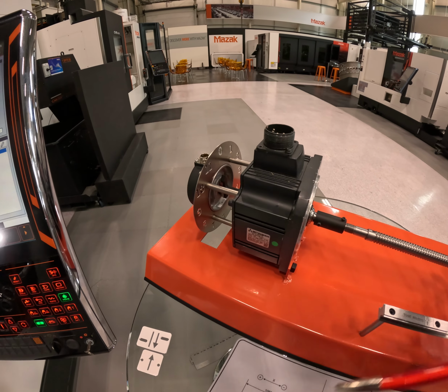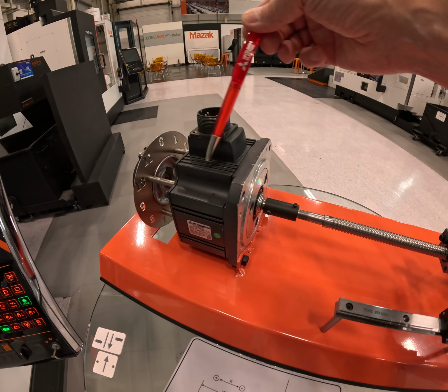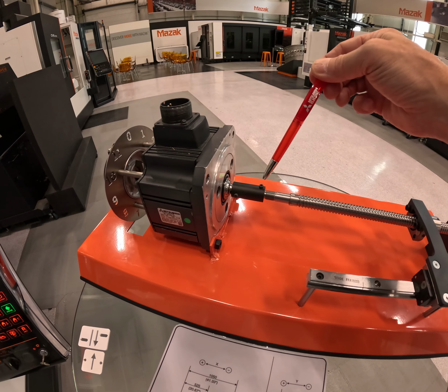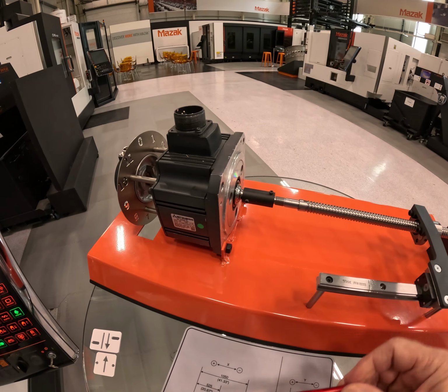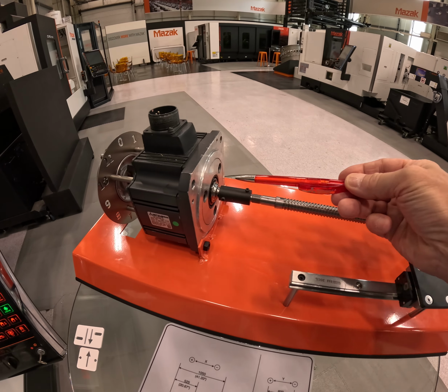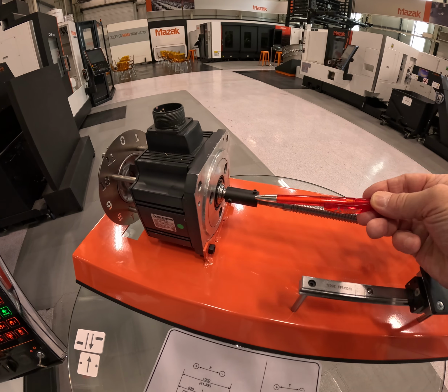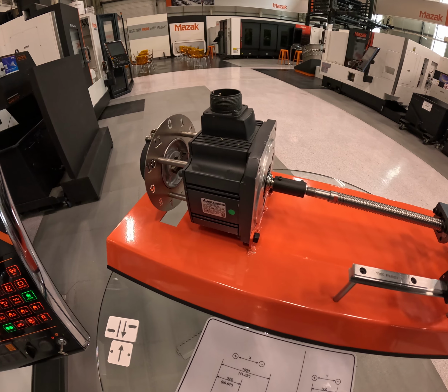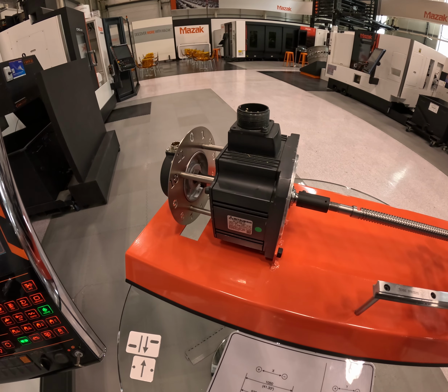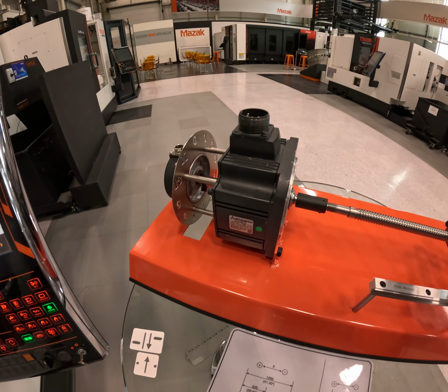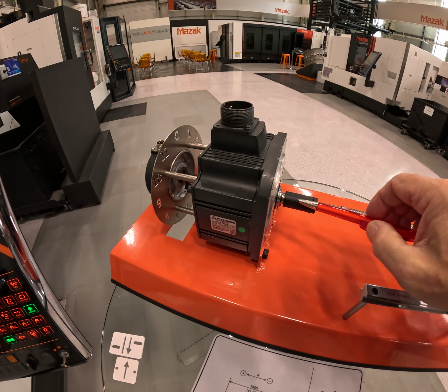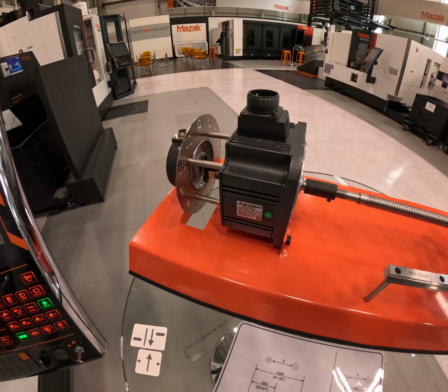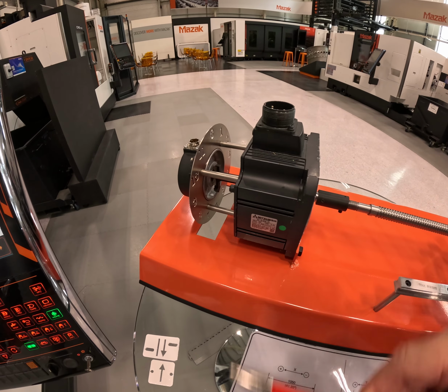The only way you're going to change that, because you've changed your motor or your ball screw, is you can undo the coupling and turn this motor or your ball screw half a turn. When you do your 0 again, because you dynamically change that position by changing this coupling, it will stop around about 6 millimeters, or half your encoder or your grid shift.